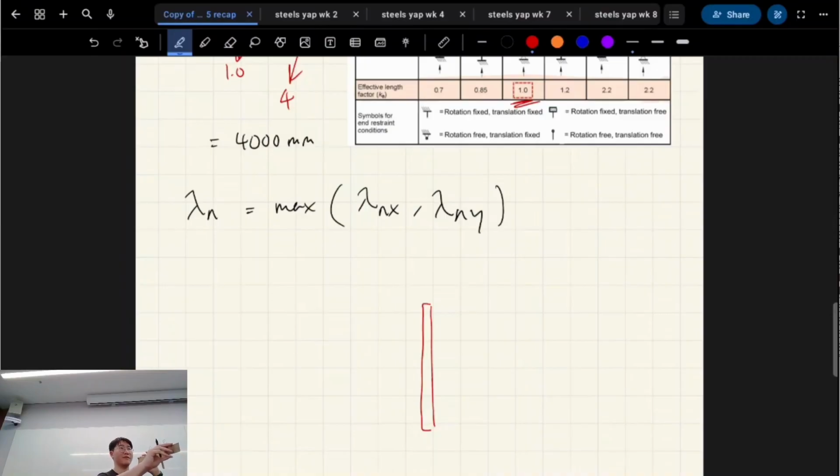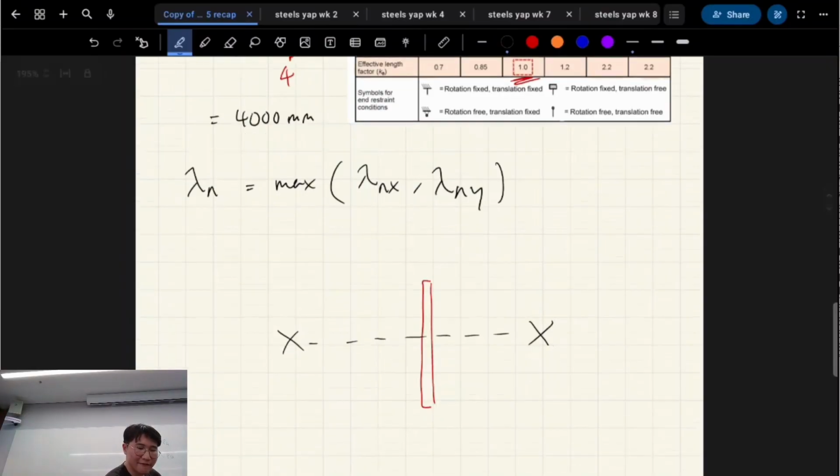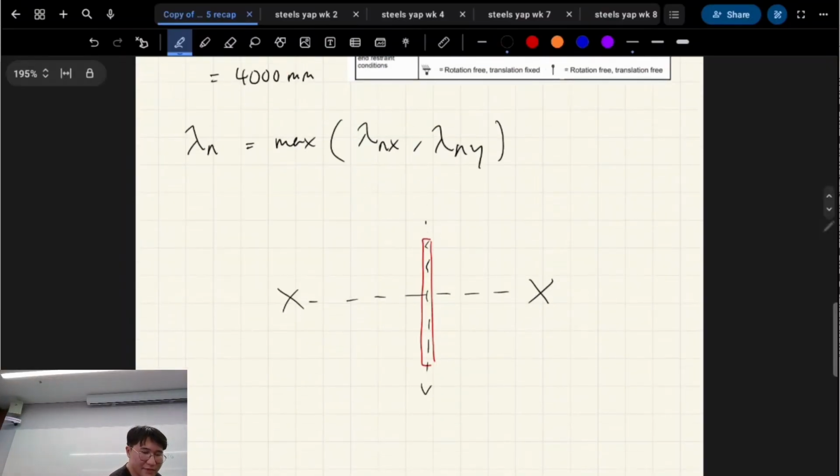The major axis bends this way. If I tried to bend it this way, it won't even really bend at all. It's quite stiff in this major axis direction. If I bend it this way, on its side, and put axial compression on it, it's going to be less stiff in bending, in buckling, I guess.